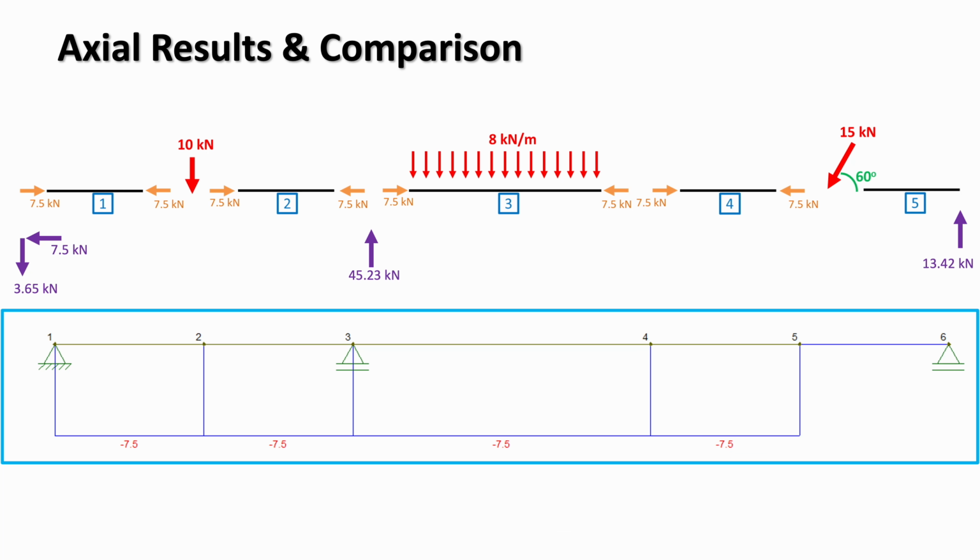On this slide, we're comparing the axial forces obtained from the stiffness method to the results from F-tool. What you see at the top is the interpretation of the axial force values from our code, drawn in their true physical directions. Compression is shown pushing into the element and tension pulling away, so any negative values have already been flipped for clarity. It's important to note that this slide shows only axial forces.